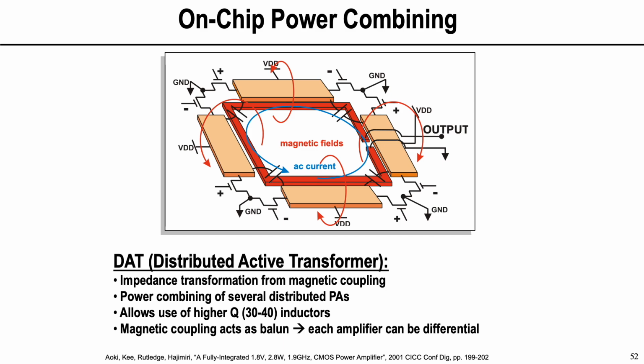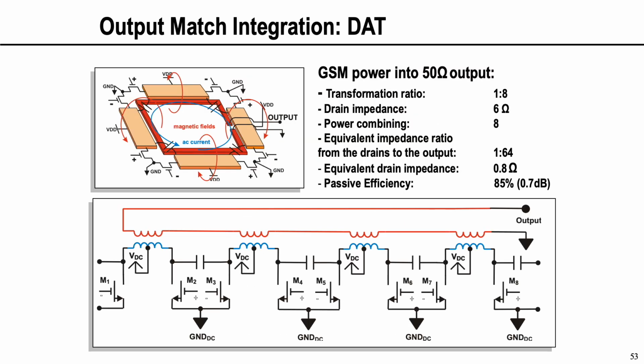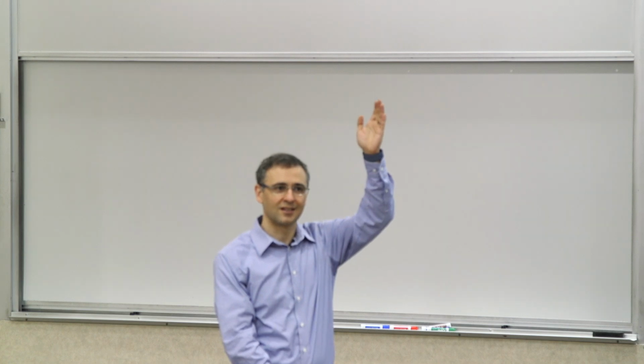And another way to think about this is that you can think about each side of this thing, the part with the primary slab and the secondary slab, as a one-to-one transformer. And you have a one-to-one transformer there where on the primaries, you're driving the primaries of these things independently with this structure that we discussed. But the secondaries of them are put in series, which allows them to add the voltages.